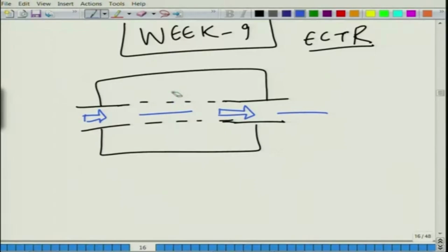So, here the only thing that is important is the grazing flow impedance. So, here only the Mach number Mg, the grazing Mach number, is important; Mb, or the bias flow Mach number, is 0. So, what is bias flow? Bias flow is when the flow has to necessarily go out of this and there is another duct and the flow again enters the other duct, which I will draw soon, and then it goes through this thing. So, basically the velocity that goes through the ducts, if that is non-zero, then you have a non-zero bias flow, or you have a cross flow element.